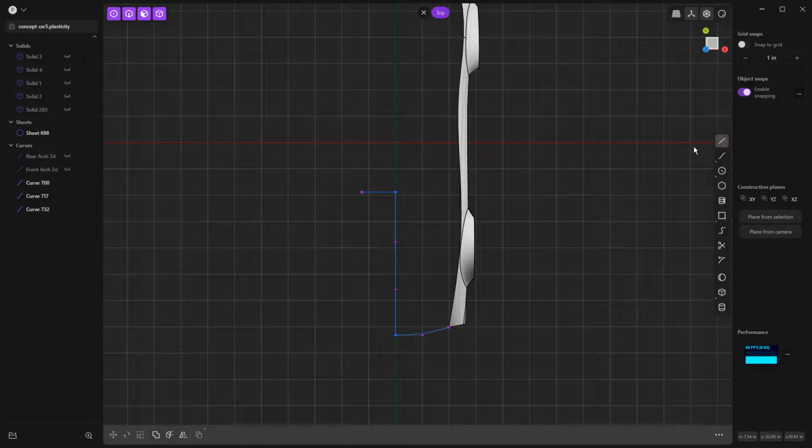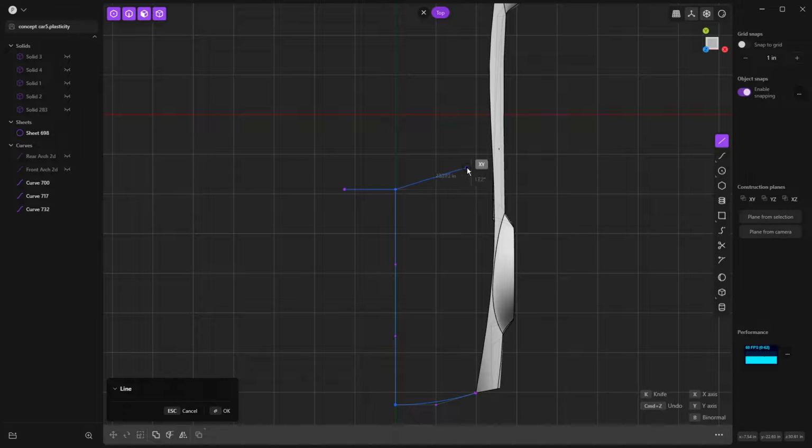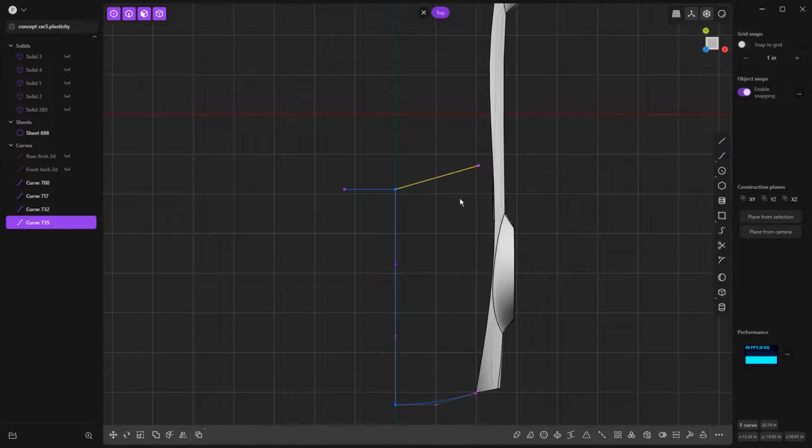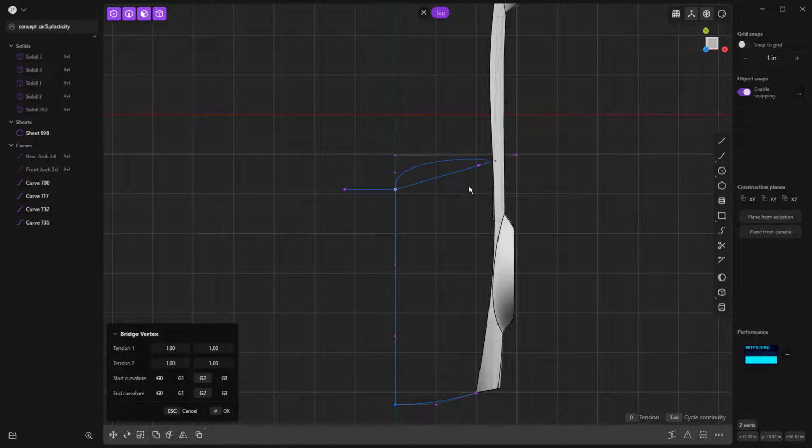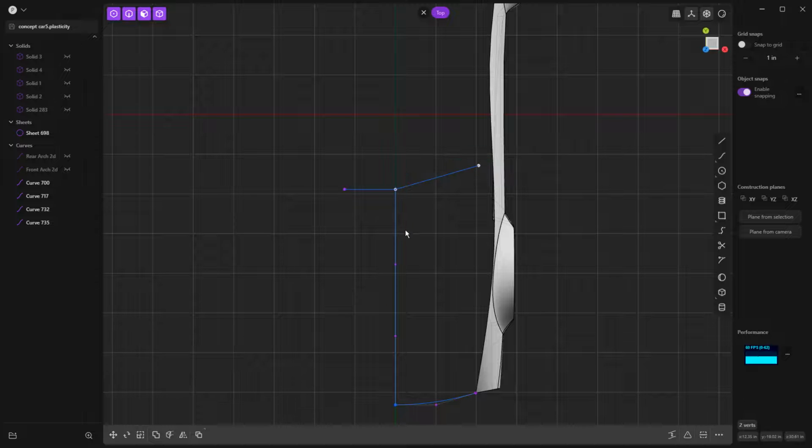And then what I can do is pick the end location, so where I think the windscreen is going to go, maybe somewhere around here. And I can select that vertex and that one. I can hit L for loft. Now notice with this, it's picked the wrong vertex. It's actually picked that midline curve.